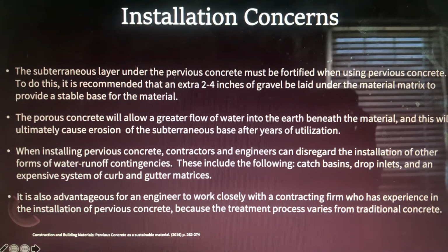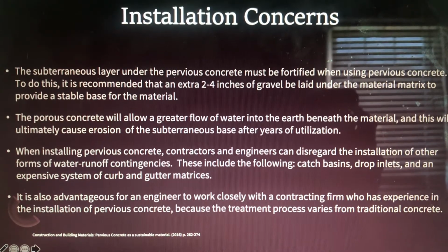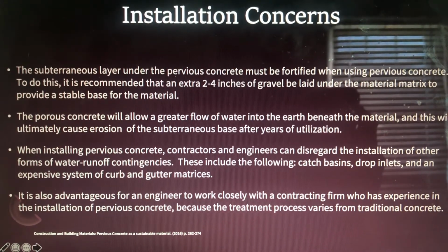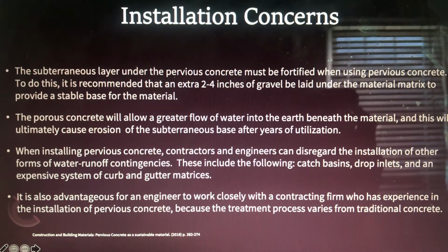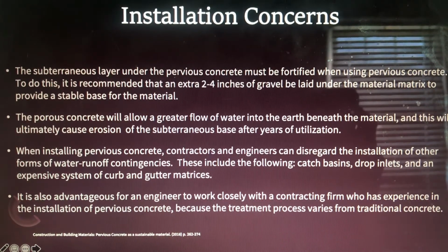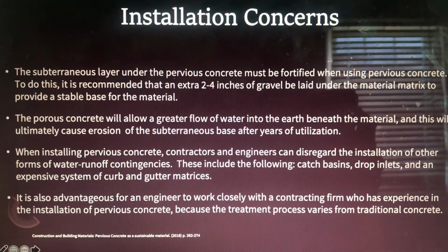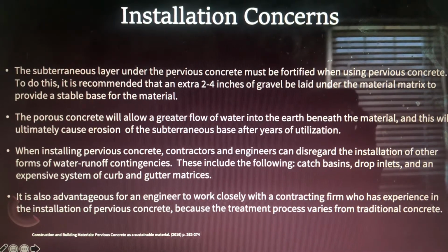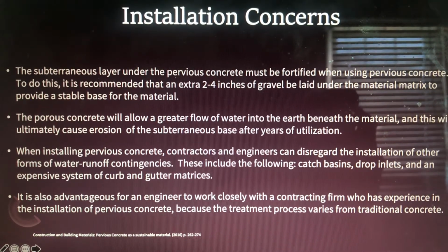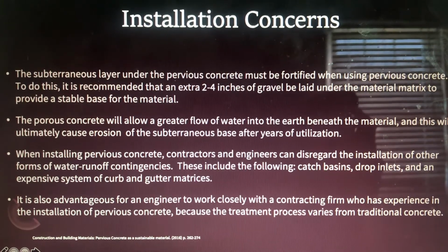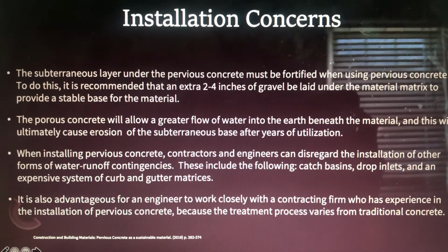But when you say you have to lay 2 to 4 more inches of gravel, that cost up front is a little bit more expensive. But when you think about the cost of installing curb and gutter and catch basins and drop inlets, and you think about the cost of flash flooding in your area, you really start to weigh these out, and pervious concrete looks very enticing to use in your project.